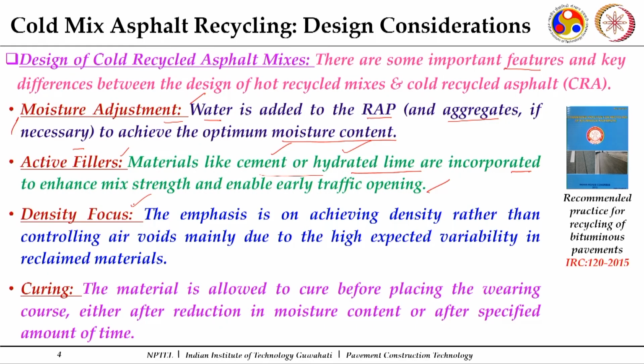The third important thing is, here the main focus is usually on the density. Instead of air void content, we prefer to focus more on density. We also go for measurement of the stability, the indirect tensile strength, and the tensile strength ratio also. So the strengths of the dry unconditioned samples and the conditioned samples are compared, as we did in the case of the hot mixes also.